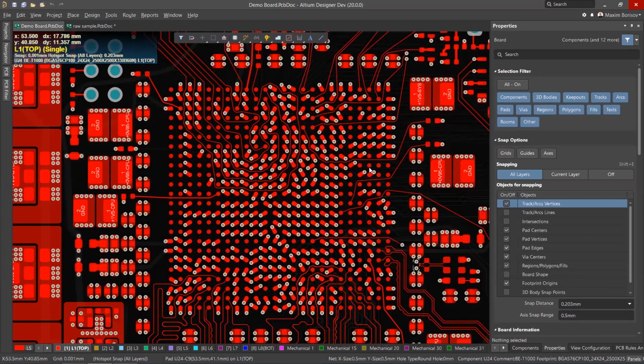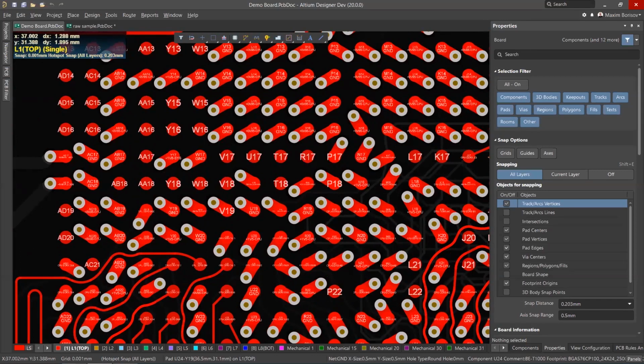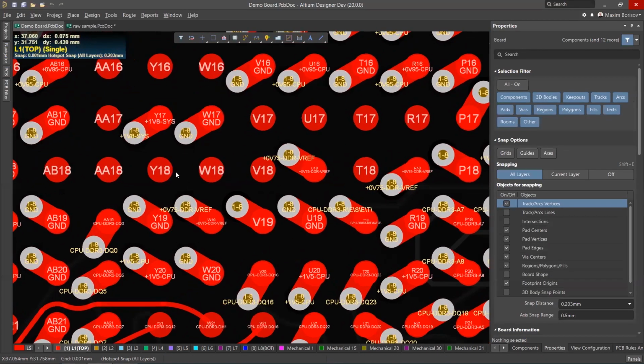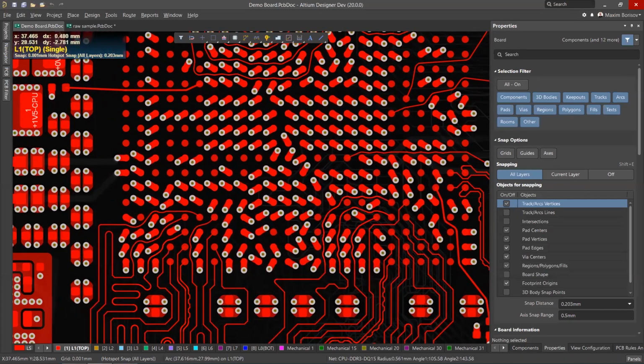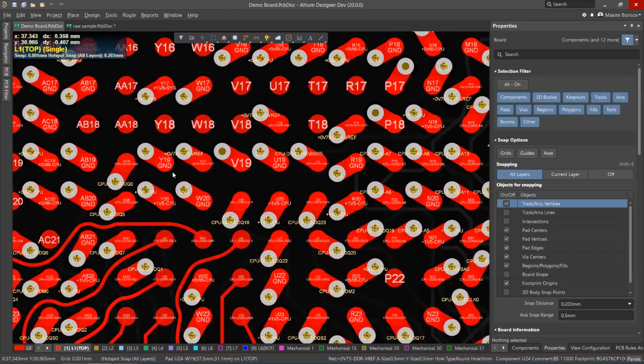First of all, you are able to utilize outer layers, and not only outer layers, much more efficiently. If you place fanouts as usual, like in the very center of this area, you will block all possible headroom to use free spaces between the paths.